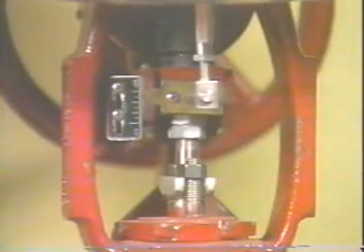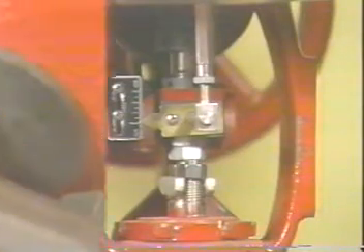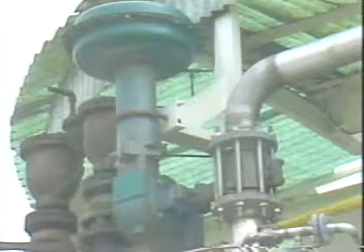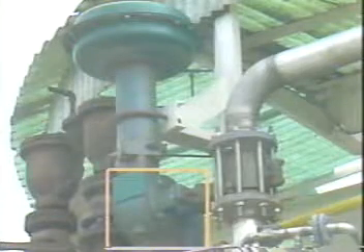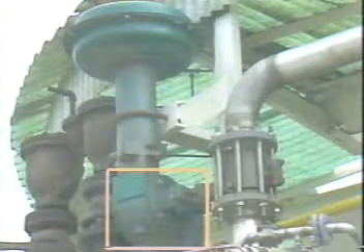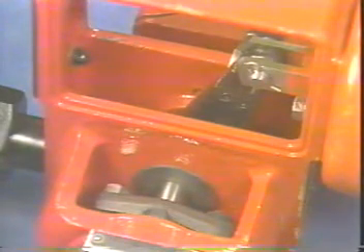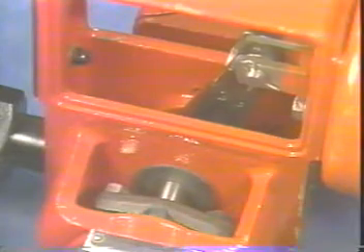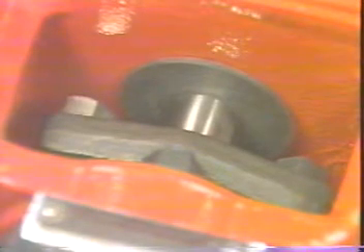Now, you may have noticed that all of the actuators we've looked at so far are for linear motion valves. However, there are many control valves that require rotary motion. Motion transfer mechanisms are devices placed between a linear actuator and a rotary valve that function to convert linear motion to rotary motion. A lever, such as this, or a rack and pinion, can be used with both piston and diaphragm actuators. You can see that linear motion from the actuator causes a rotary motion in the valve stem. These devices are usually limited to 90 degrees of rotation.